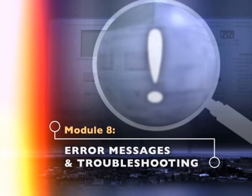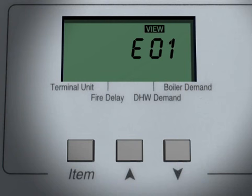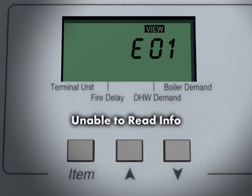To simplify troubleshooting, the control will display an error message under certain circumstances. Once the situation that caused the error message to display has been corrected, the message can be cleared by pressing the Item button. Error message 1. The control was unable to read a piece of information. This can be caused by a noisy power source. The control will load the factory defaults and stop operation until all the settings are verified.